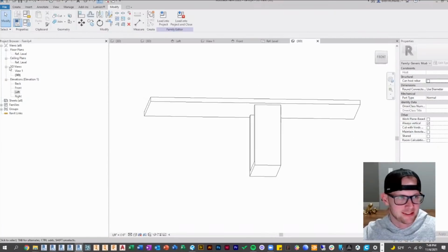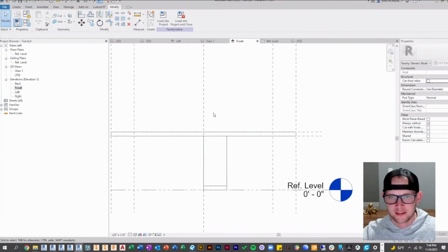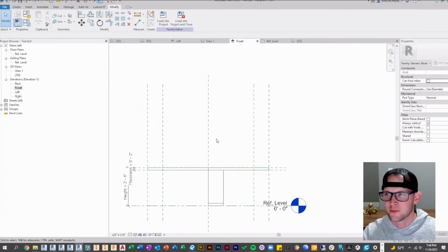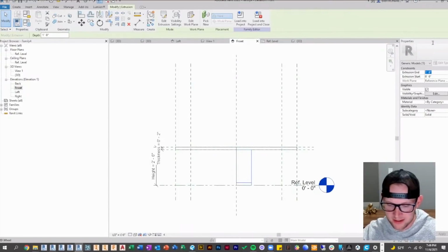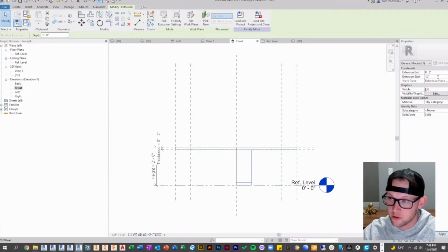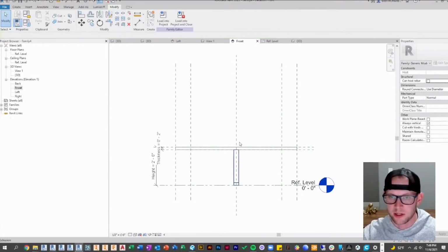And so, right, this is the other thing. It assumed when I did that sketch, it assumed the center line was the sketch plane. So we're just going to really quickly, I want this 4 inches wide. So I'm going to split it across the hosted plane. We'll just do 2 inches in one direction and negative 2 inches in another. So then it just split it across that plane.